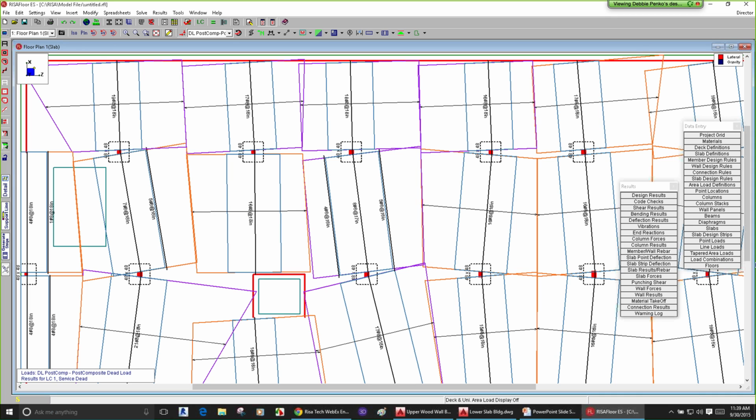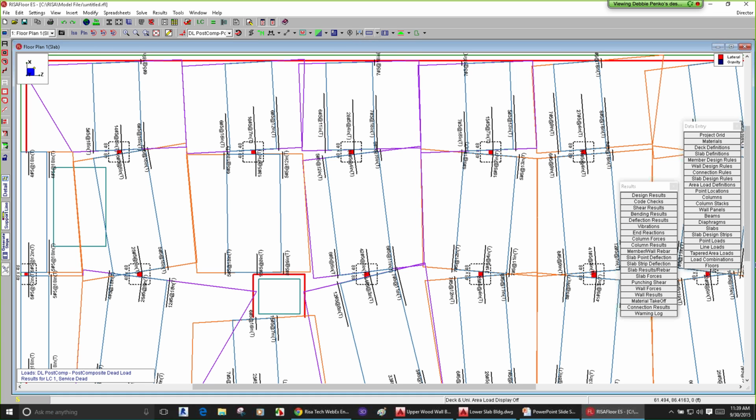So when they're common here, so this one's at 18, this one's at 18, it's going to go across there. This one here is at different spacing. This internal one here, this column strip needs a 17-inch. So you'll see it tries to fit them all the same if they can. If we can go to the top, let's go to the top bars. You'll start to see here, we're going to be in the top bars, number 5s.